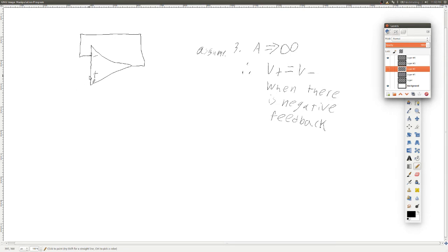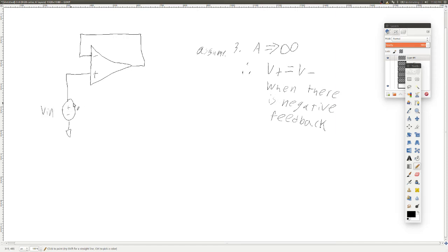Specifically, it means that we can use the nature of an op-amp to actually do some circuit design tricks. For example, let's say that we have a very, very weak input signal, Vin over here, something which could not handle if there was a very small resistance that led to a lot of current. We would deal with what's called signal degradation.